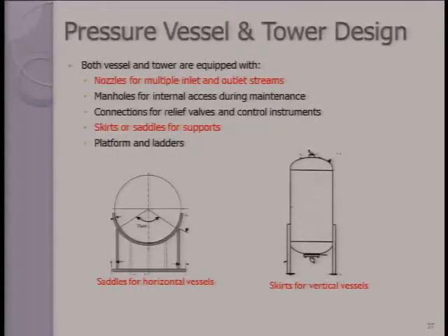For example, when you design your continuous flow reactor next semester, in addition to choosing the diameter and the length, you also need to choose the nozzle size. Because the nozzle size will influence the velocity of your reactant going into the reactor. And when you have a packed bed, the velocity will influence the pressure drop. The pressure drop for a gas phase reaction will influence the concentration, so it will influence the reaction rate as well. That's why the nozzle selection is important. It's not something that you can ignore.